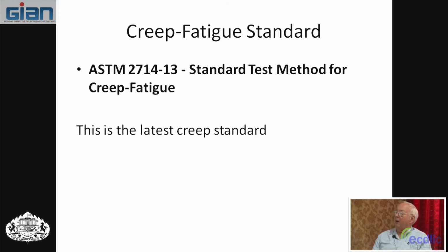One of the bigger problems is creep fatigue, and there's a standard that was developed just a few years ago. It's the latest thing I found. Notice the ASTM numbers are chronological, like K1C is E399. This is E2714. So that's how many mechanical test standards have been written as of this time.